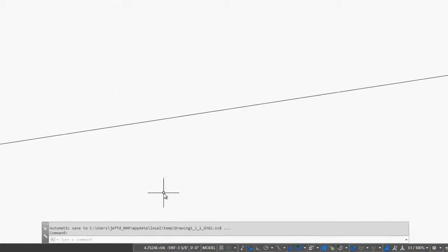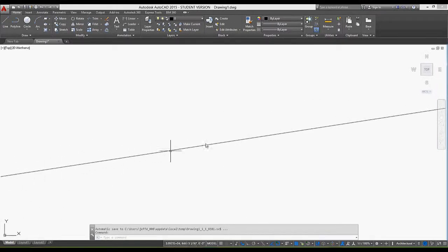What it does is it zooms to the extents. So it zooms to the extents of my 10,000 foot line, and that will essentially break the drawing limits that AutoCAD has imposed upon my drawing. Now, I know to begin with this is a much longer process. You're like, well, why not just put in the limits and have that be faster? When you start to get used to this more and more, I find it's just the fastest way of doing it.